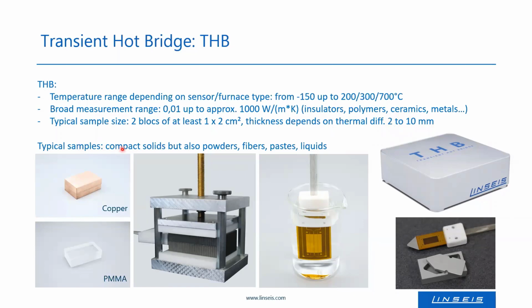Typical samples are compact solids, like those metal or polymer blocks, but with the help of such adapters, which may be filled with powders, and a metal frame enforced sensor, which is used as a penetration sensor, also powders may be analyzed, and also fibers. And just by dipping a sensor in a liquid or a paste, you can also determine thermal conductivity of pastes and liquids.